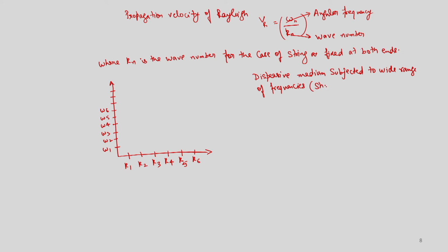By means of shock waves, which you generate by means of hammer impact. So, what will be the response of the MDOF system? It can be like this. If you join these, based on equation number 3, one can understand how much the propagation velocity of the Rayleigh wave will be.